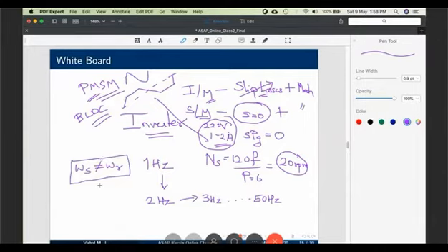So during transients, omega is not equal to omega r, then delta will increase, and there is a possibility that delta can go beyond 90 degrees and cause instability issues. That is the reason why this TSM, true synchronous mode of operation, has certain issues.